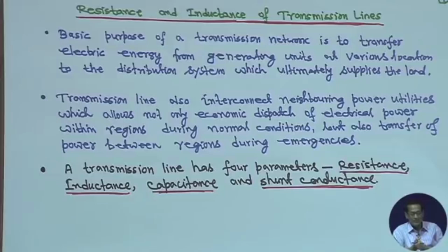It depends on the voltage level; different conductors have different resistance in ohm per kilometer, as well as reactance. Of course, there are bundle conductors and double circuit lines. When you have seen a high tension transmission line, each phase may have 2 or 3 or even more conductors, bundle conductors, and sometimes single conductors in each phase.